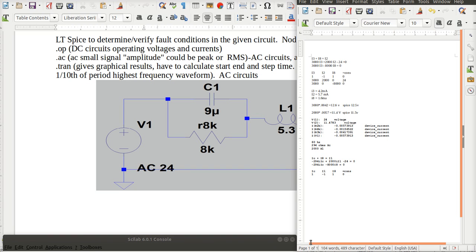So what you see is our first equation didn't change based on the way we picked current direction in the DC circuit and the way we picked current direction in the AC circuit. Our current directions didn't change. There are no imaginary terms in the current. Our currents will actually come out to be imaginary numbers because they're phase shifted, but in terms of writing the equations, it's not. So I'm going to do the same thing up here that I did there.